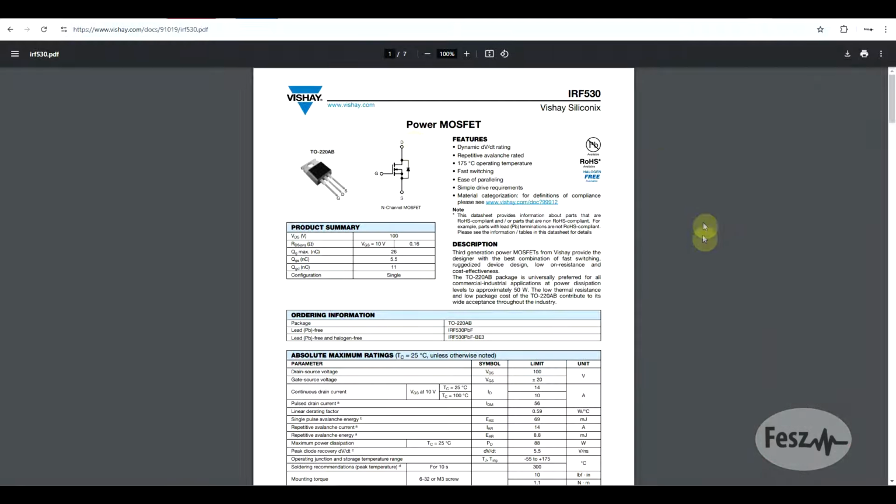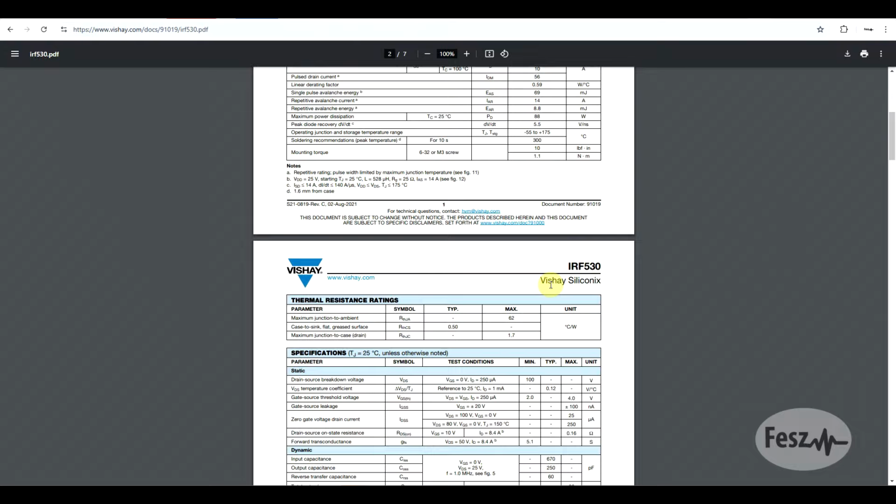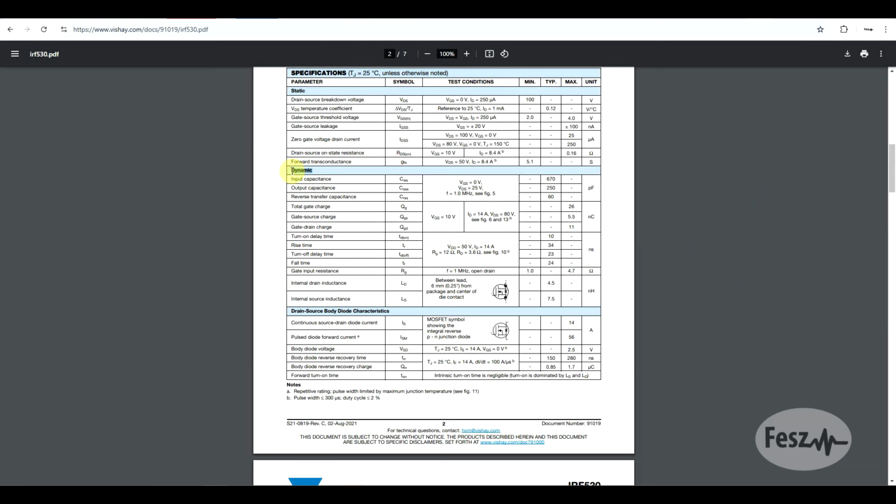So now let's focus on the main element of a controller-based supply, the transistor itself. So here, there are a few things to look out for. When looking over a transistor's datasheet, there are a lot of critical parameters to keep in mind. However, on the topic of the day, you should first look at the dynamic characteristics, and specifically at the transition times that the transistor presents. You can always make the transistor switch slower, but you can't really make it go faster. And the other important aspect will be the various capacitances. Can you actually drive the transistor, and will your system be stable?